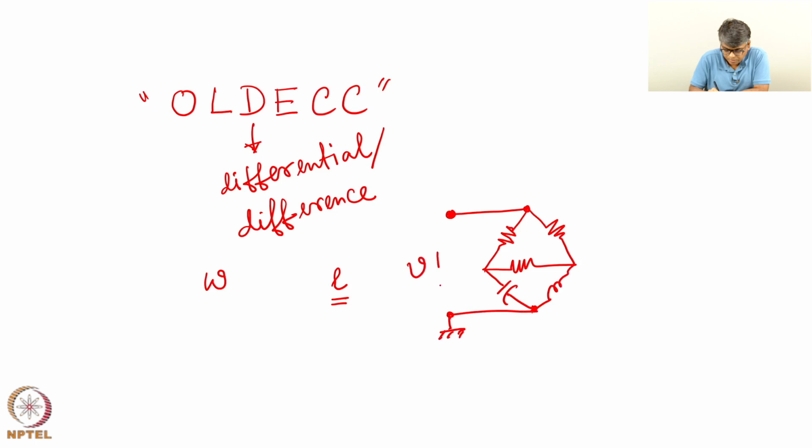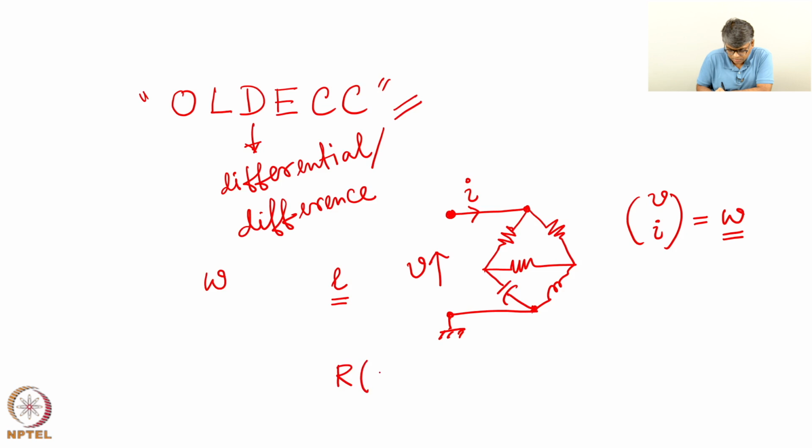The variables that we are actually interested in are these port variables, namely V and I. So we should ideally write equations involving V and I only. This is my W. If I want the system's behavior, this W must satisfy some ordinary linear differential equation with constant coefficients, which means I should have some polynomial matrix R(d/dt) acting on the variable pair (V, I) equal to 0.